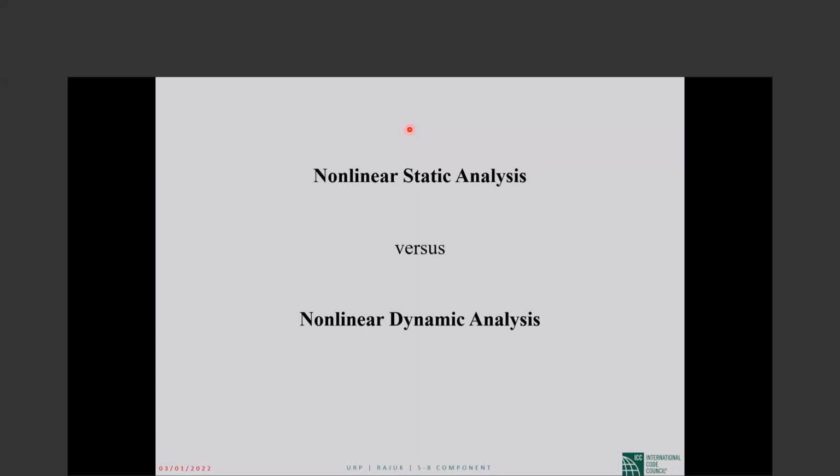For example, the earthquake happens somewhere, you have the records, you have the building characteristics, you model the building and apply the record and check whether the observed damage and the calculated damage are similar or not, and you get lots of good points about the modeling, for example, why the results are not the same. If I change the modeling of this infill this way, the results become similar, and lots of good points result. But this is where we have the record.